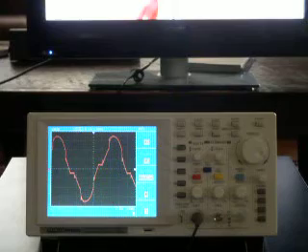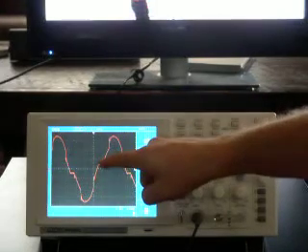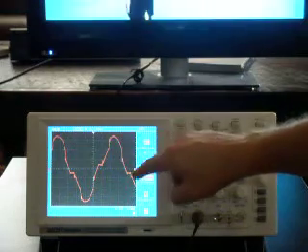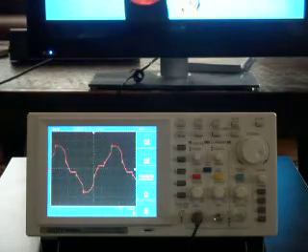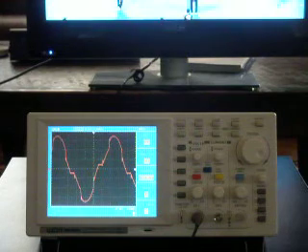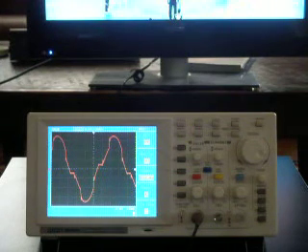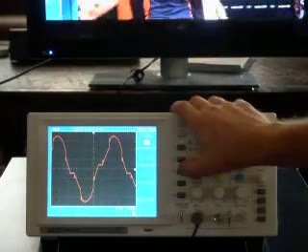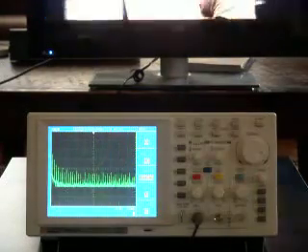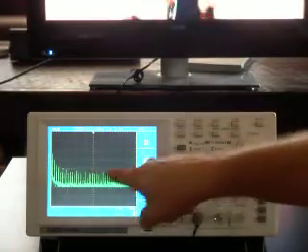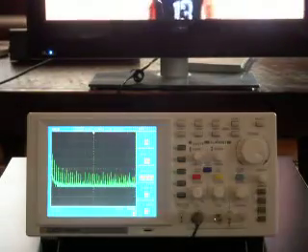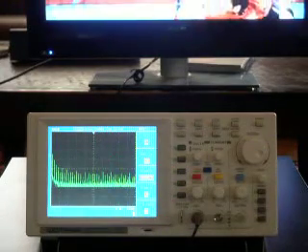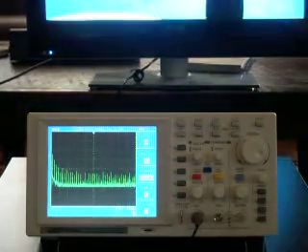And what you can see is all of these little notches and severe angles that you see on the waveform, these little ringing effects, they're all part of harmonics. And I'm going to show you the harmonics. I'm going to turn on a function called the fast Fourier transform function. And coming in this direction from left we have 0. All the way coming over here, each division goes up in 500 Hertz divisions.